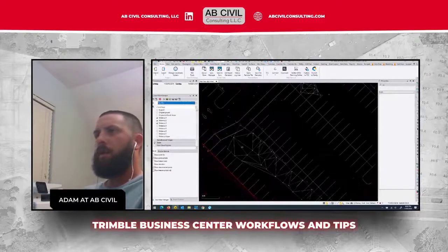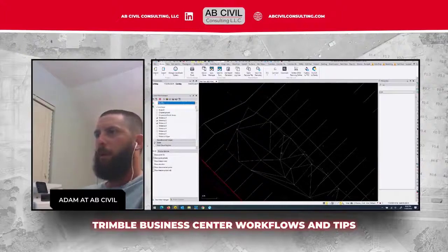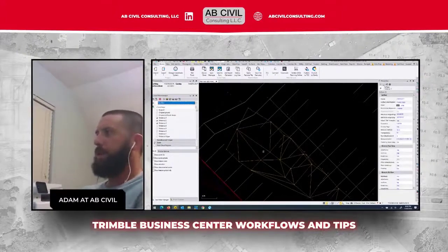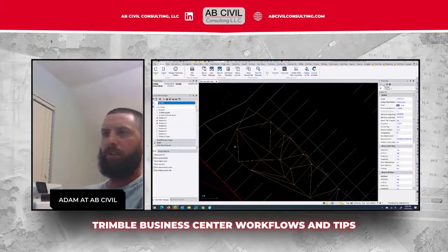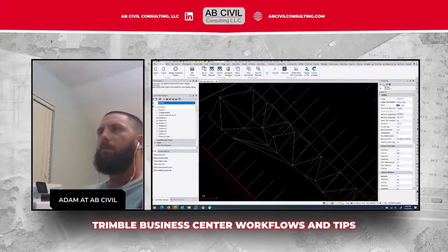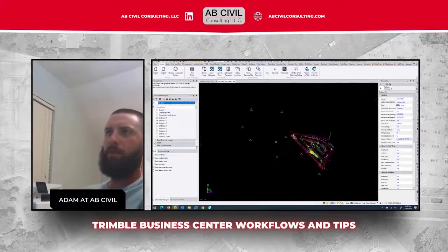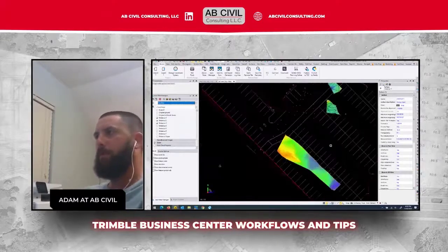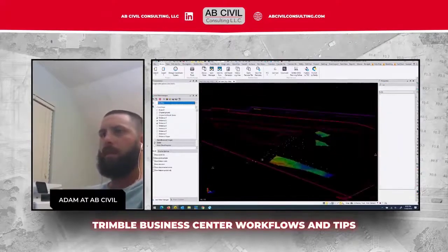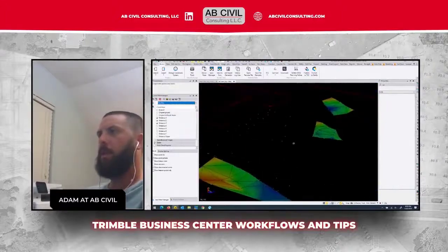All right, so the first thing I did was bring in the points from the topo. These were probably the first 3 that I did. I just created a surface out of all the points. Nothing special. I don't worry too much about break lines, especially when someone provides me a topo without much information. So in 3D, that's what they look like.